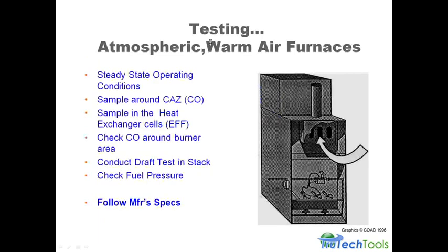All right, efficiency testing. If you download the Testo combustion guide, which is free on our site, if you just search for a combustion guide, you'll find it. It goes through where to test all these appliances and how to test them all. But with atmospheric draft, the key thing you've got to remember is you've got to sample undiluted flue gas.